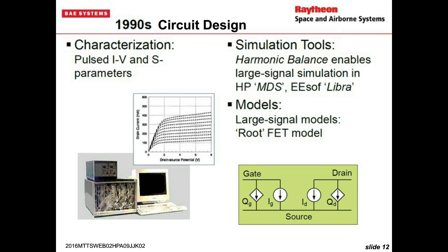And then you would match the voltages and currents at the junctions between the nonlinear elements and the linear elements in an iterative fashion using things such as a Newton-Raphson optimization to converge the two to an answer. So for the first time, we could do real nonlinear simulations using basically a linear tool that is very efficient.